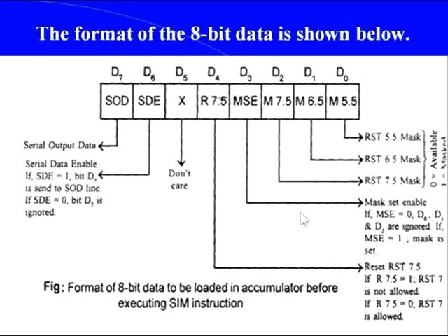Bit D4 gives additional masking facility for the interrupt RST 7.5, one more extra facility. If you want, you can reset that interrupt by using this SIM instruction itself.